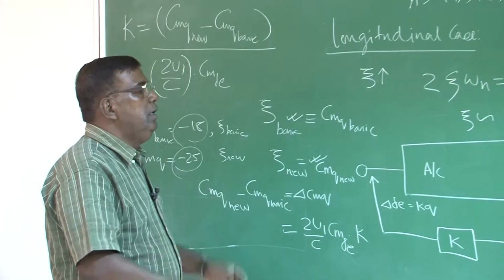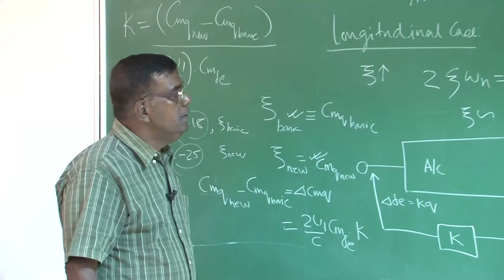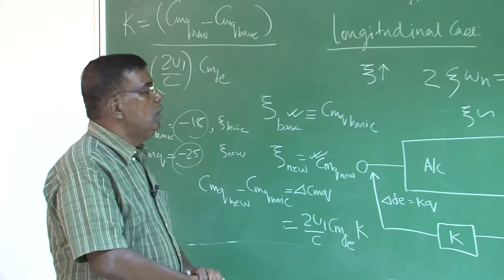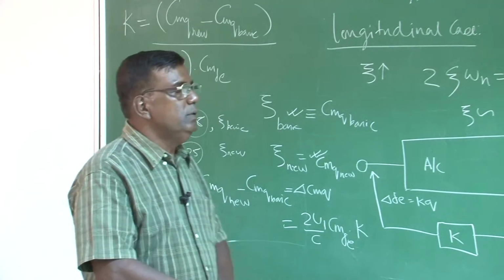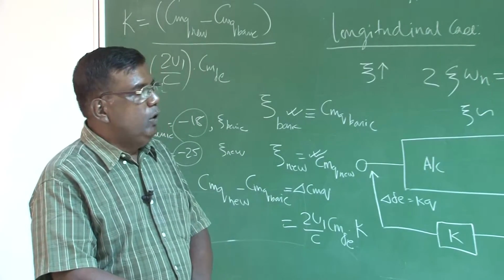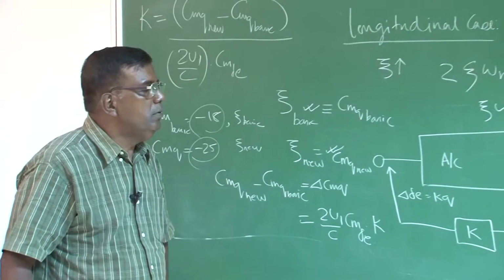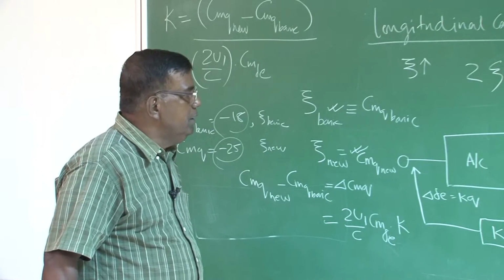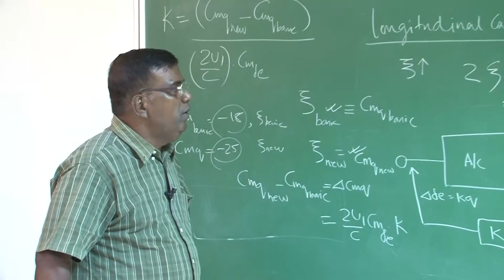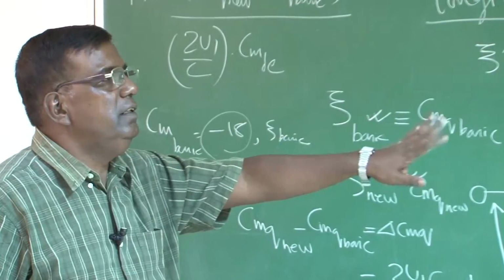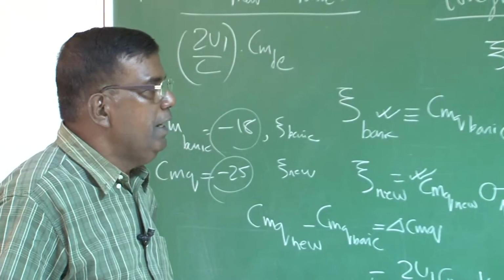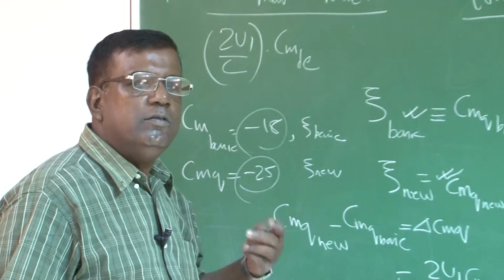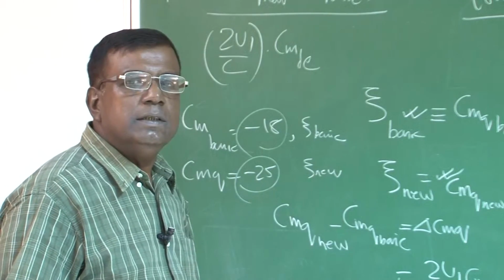And similarly, we'll build for the directional case, lateral case. If you understand this much, you yourself will be able to extend this understanding to the lateral directional case. We'll do that in the next class. And I'm going to talk about handling qualities soon. But I thought before I talk about handling qualities, you should demystify all these SAS and all. This is basically the concept. That's all, right? The rest is solving the six-degree-of-freedom equations of motion or finding a transfer function and their solution. The understanding is this. Okay. Thank you very much.